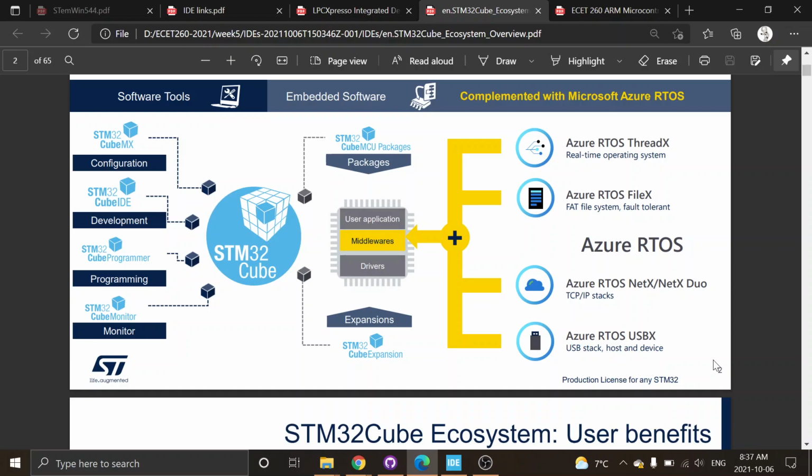Now I want to add an A to D or add a DAC or add some USB. And the engineers that did those examples didn't use the Cube IDE, and so it makes it hard for you to add things. You have to go and make the structures yourself and put all of that in.